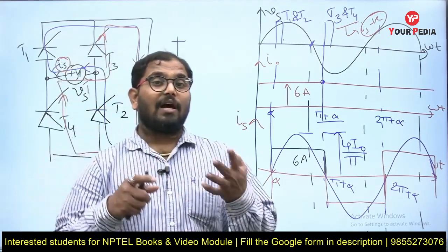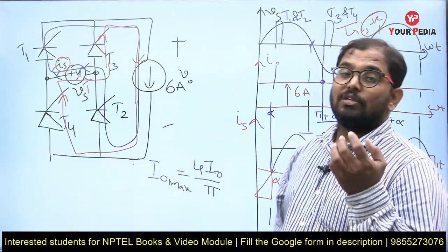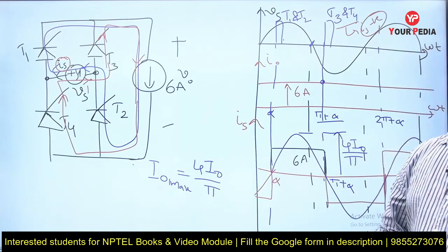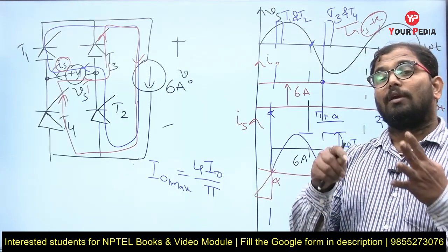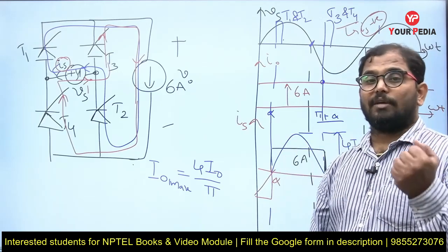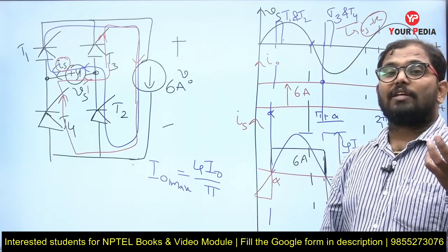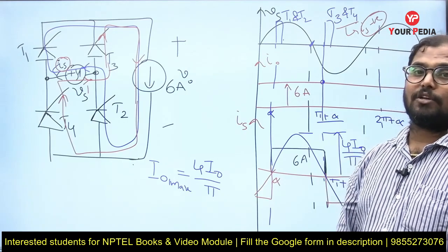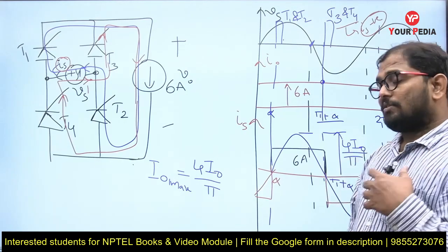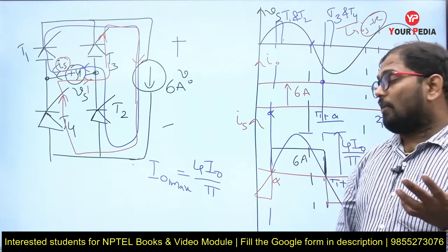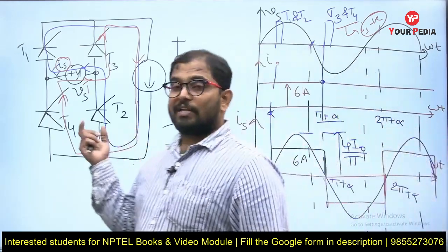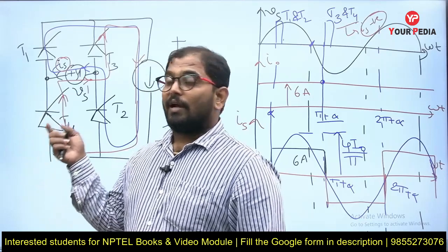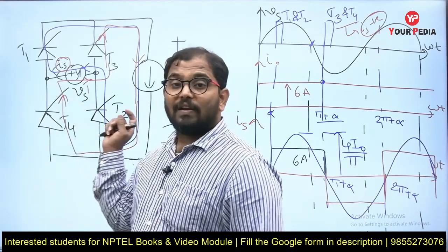Each and every harmonic will introduce some torque. Some torques will be opposite to the original torque, and some will be in the same direction as the original torque. This will create extra problems in the system, which can be avoided by using filters. That is the reason a source filter is required at the source side, and a load filter is also required at the load end.